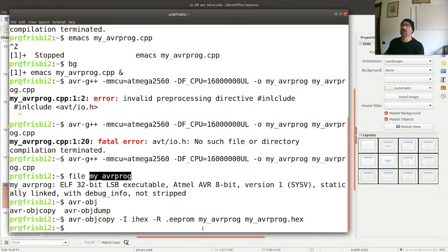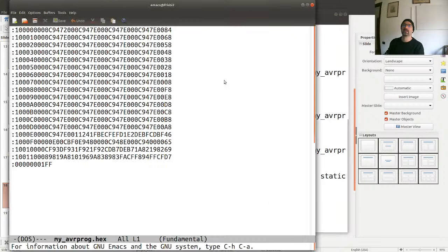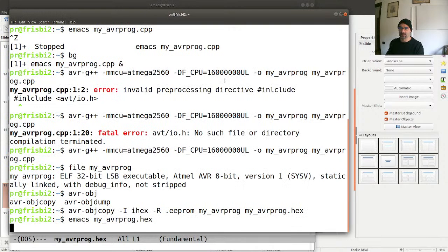Okay, and then this program generated another thing, which is myprog.hex. How does this look like? I'm opening it with an editor. It's a bunch of hexadecimal numbers. They are lines that contain, this is clearly a control sequence, I think. This is the address, then there will be a control sequence, and then at the end there will be the instruction to be written in that location.